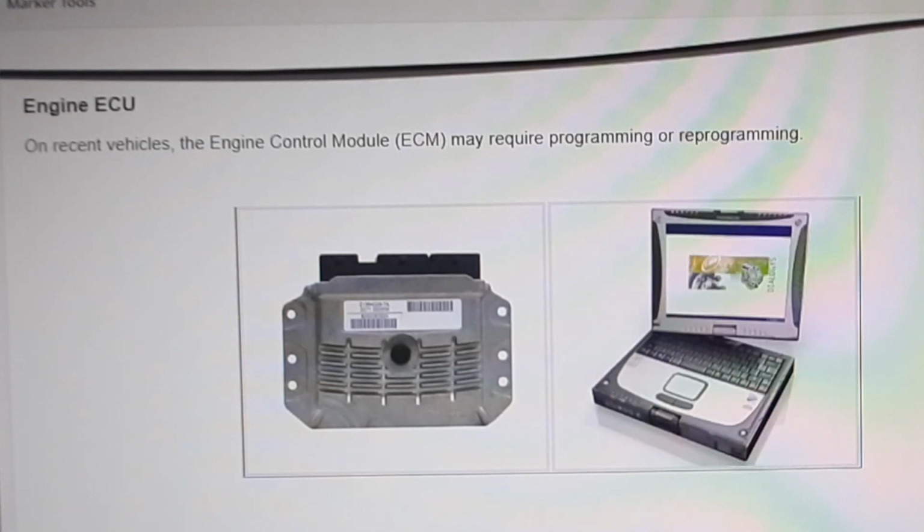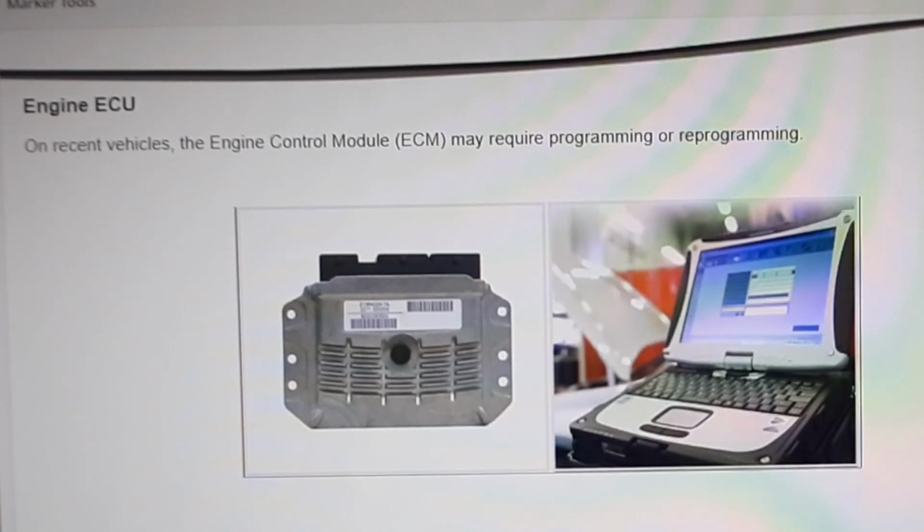Also, when installing a new computer, a number of programming operations need to be carried out, such as programming the immobilizer code. Since the immobilizer code programming is permanent, carrying out tests with injection computers borrowed from the parts department and that need to be returned is prohibited.